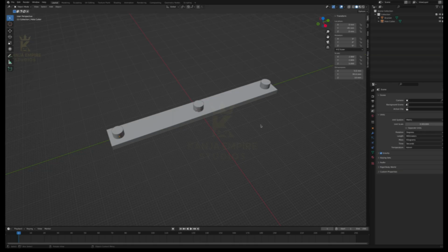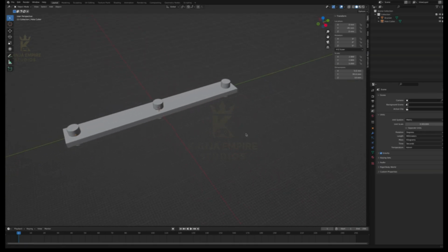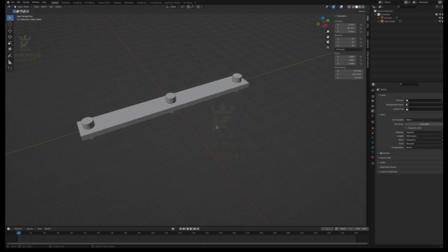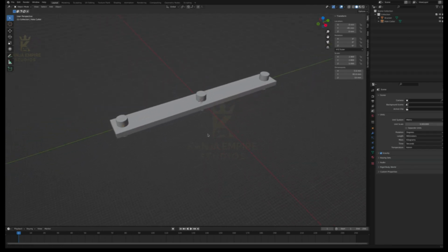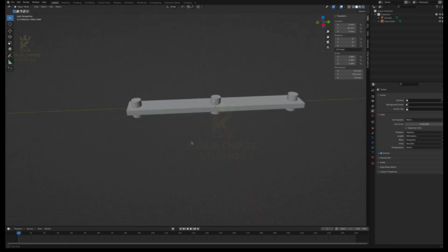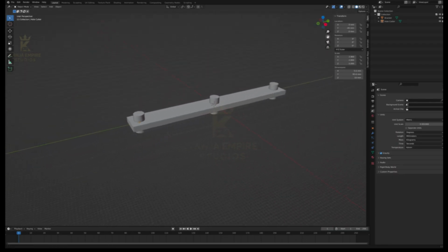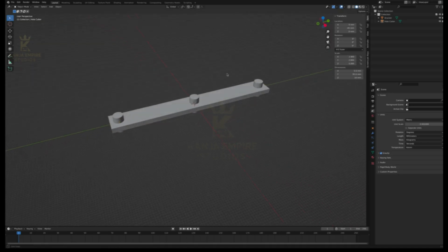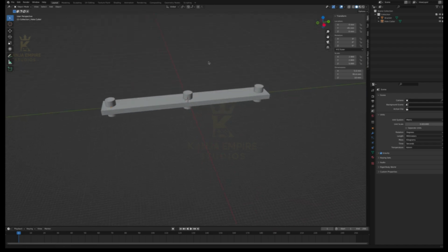And now also I wanted to mention, I forget if I mentioned how to pan on the screen here. If you hold shift on your keyboard and the middle mouse button, you can pan side to side, up and down. And the middle mouse button alone is just to rotate. And there's also the shortcuts up here. You can pan by holding this button here. Yeah, so I forget if I mentioned that, but that's an important thing to note. So you could practice moving around the scene like so. Okay, back to the hole cutting here.